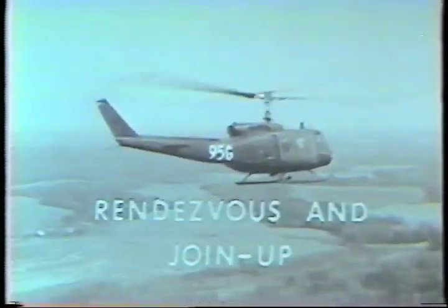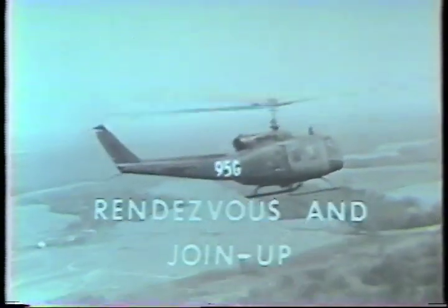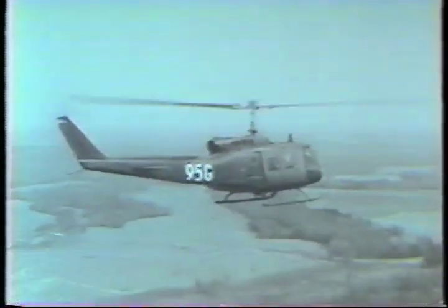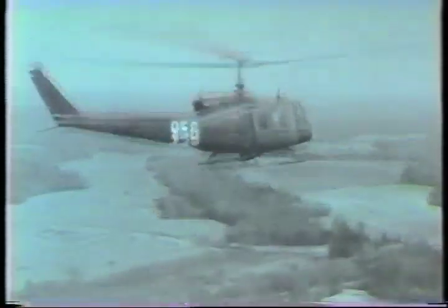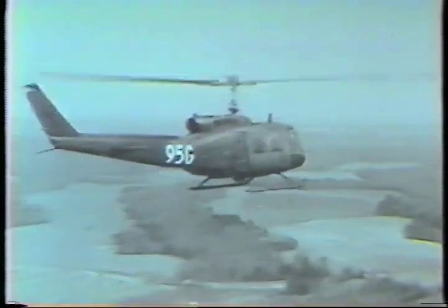The functions of the flight leader in formation rendezvous and join-up are to approach the rendezvous point at a pre-planned time and altitude. Upon reaching the point of rendezvous, the flight leader will enter an orbit in the pre-planned direction using a standard rate of turn and an airspeed of 60 knots.